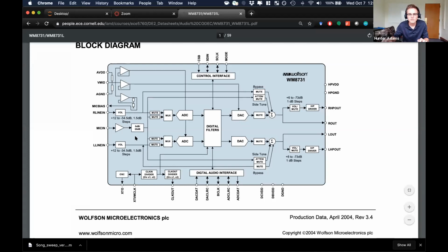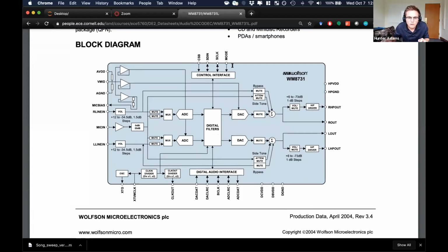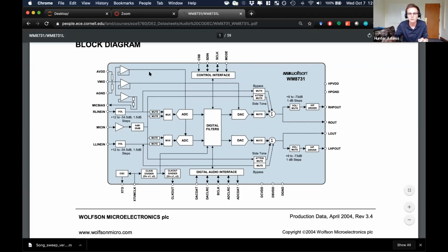What else is of interest to point out here? It enables you to mix these various signals together, so you might be able to do something interesting with that. It has a couple of interfaces. This whole thing is configured through that AV config module that we drag and drop onto the QSys bus. So that talks, as we've discussed, through an I2C interface that lives up here.